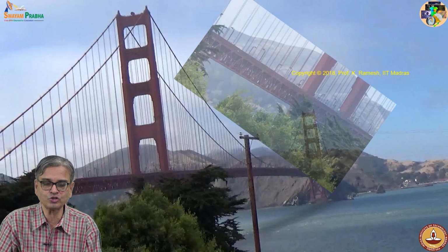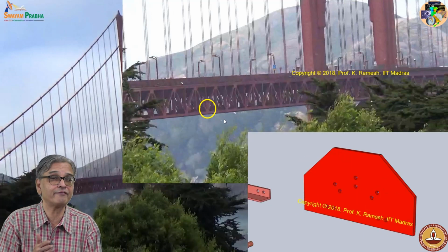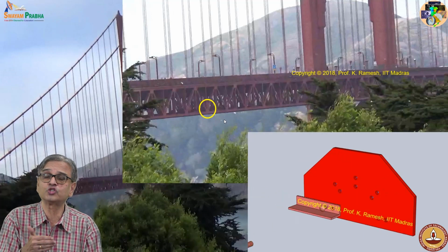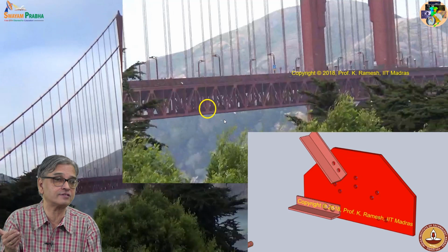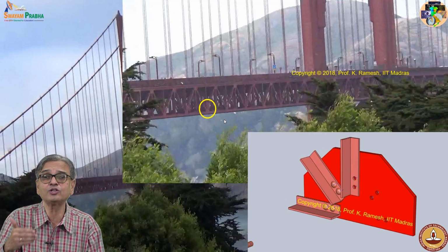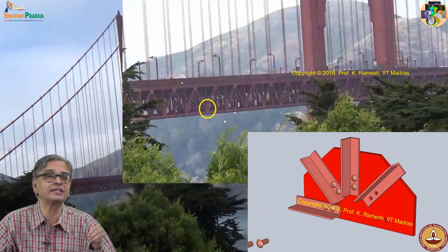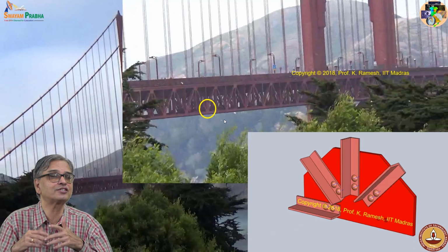So, if I have a closer look, I can see the truss and I can also see a joint, how it is constructed, and you have learned that at this joint you should have a concurrent force system. You have a gusset plate, you join the members, all that you do carefully so that none of the members forming the truss are subjected to bending.